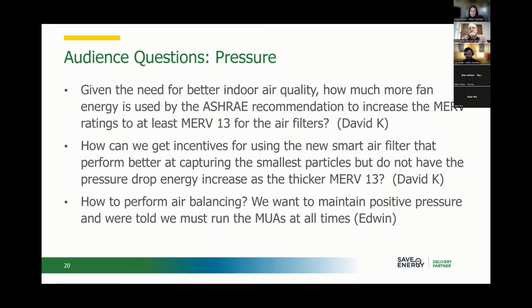And because the pore sizes are that much smaller, particles at the low end range of the size, getting down into the 3 micron size, for the MERV 8, they might flow on through, but with the MERV 13, they're now trapped. And so even though these filters may not have that big a difference in pressure drop in the beginning, you may find very quickly that the MERV 13 fills up and has to be replaced more often.